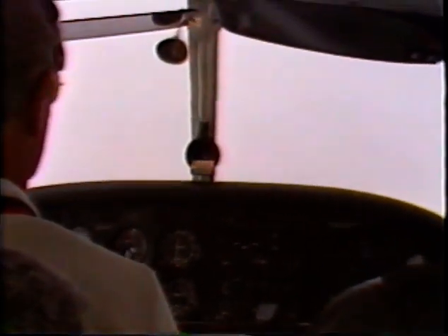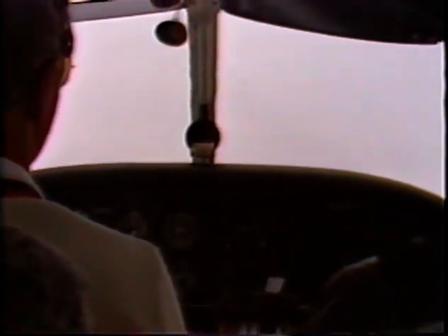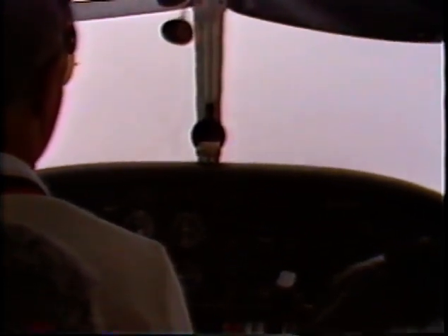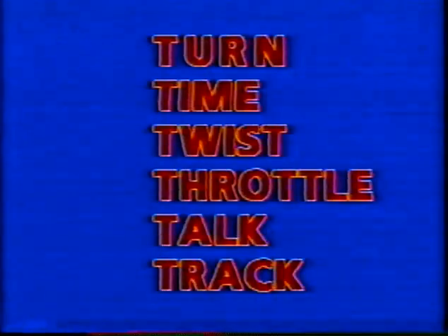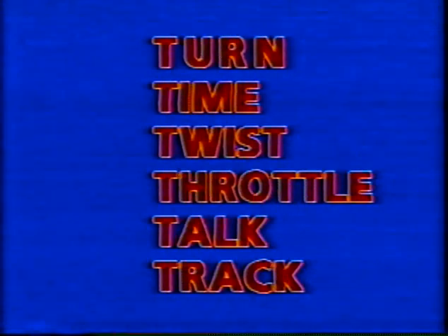An instrument approach requires flying specified courses and altitudes for particular lengths of time, radio setup, and ATC reporting. To ensure that all tasks are performed at the right time and in the right order of priority, a reliable technique is required. The 6 T's is a time-tested technique and should be used without fail every time you make a turn and every time you cross a fix.